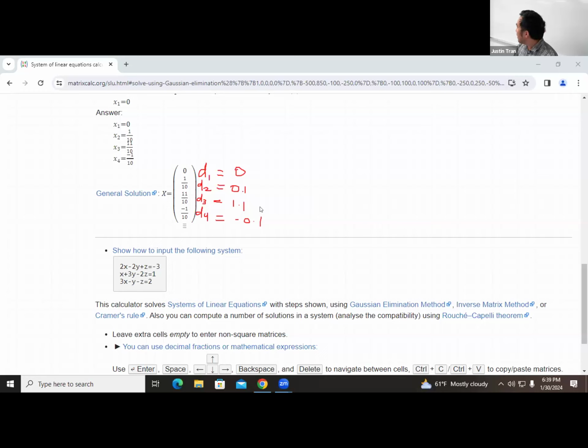Any questions on this process here? Yes. So you must have both boundary conditions to solve this problem? Yes, you need the Dirichlet and the Neumann boundary conditions. So if the right side was fixed, you can solve it? Exactly right. You need a Dirichlet condition, otherwise it's unsolvable. Physically, what that means is that if you don't have a fixed support and you apply a force, it's just going to have a rigid body motion. It's just going to deform forever. You need the Neumann conditions because without them, you have no deformation, because that's actually what's forcing the system.